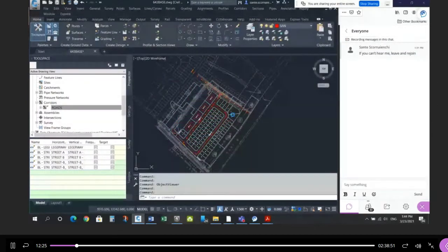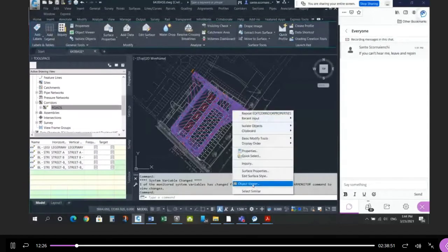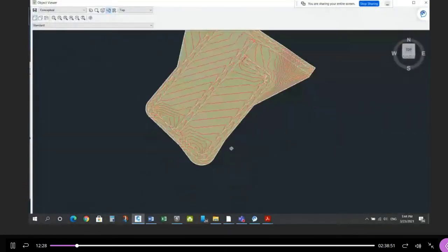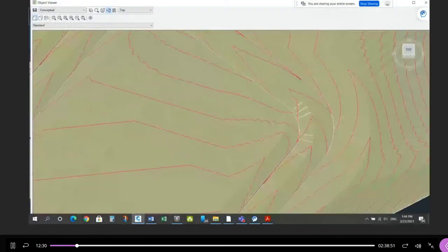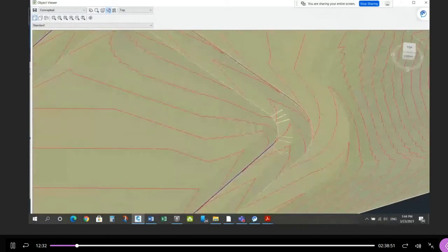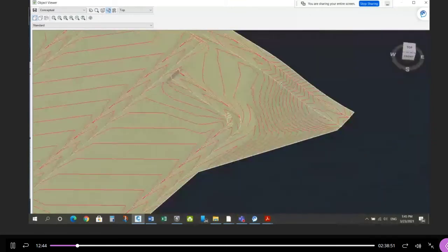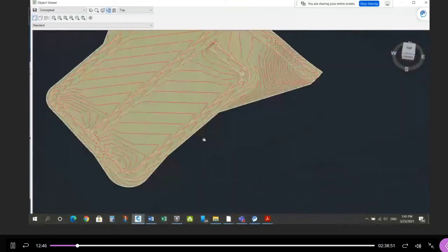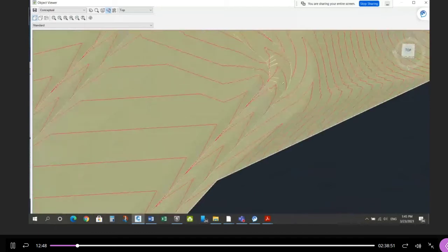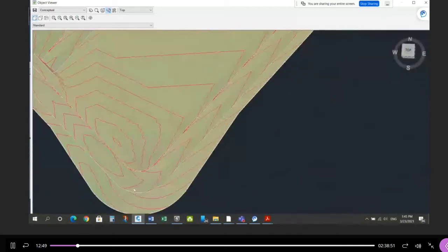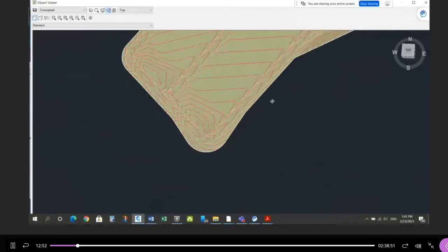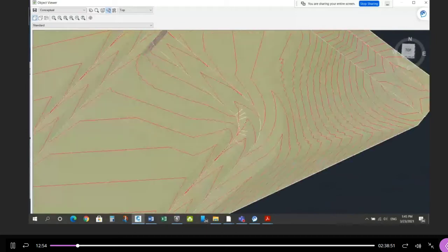Okay? So watch the surface when I look at it in 3D now. Object Viewer, and you'll see some funny business. Now it's not nice and smooth. There's some wonkiness going on in the pavement, okay? And that's a telltale sign that the corridor targeting link is wrong. Some of them are more drastic than that, but that's basically the kind of thing you're going to see, that kind of ripple effect. Whereas you can see the other one that I didn't change is nice and smooth. All right, so that's the telltale sign. I look at the surface for that.